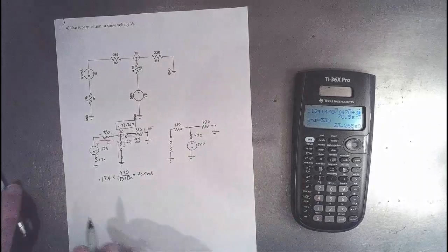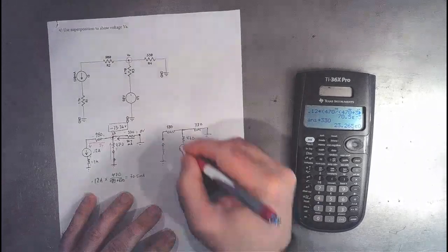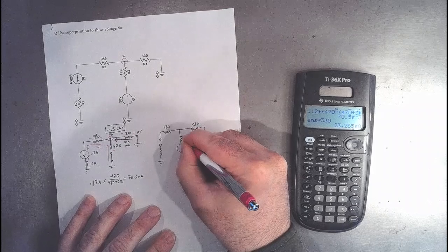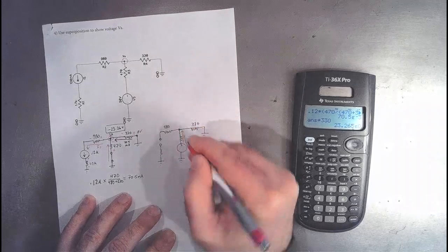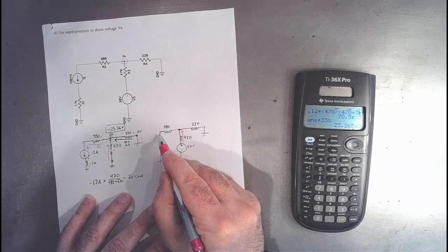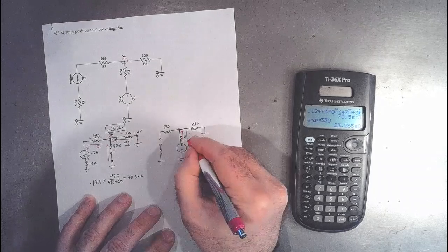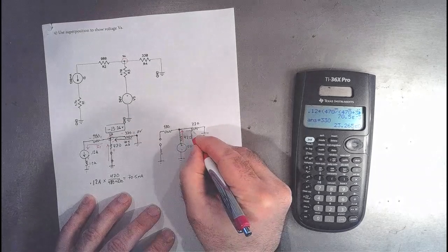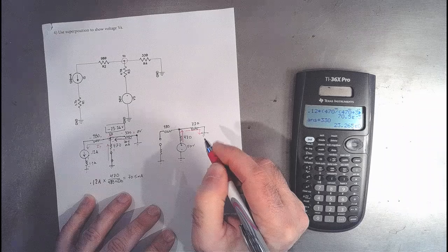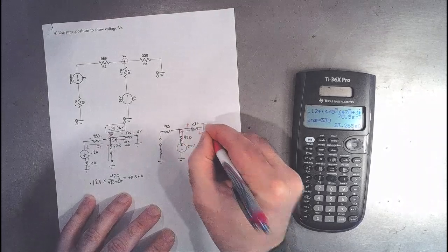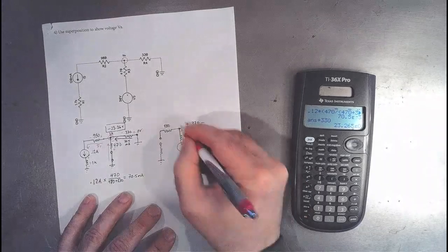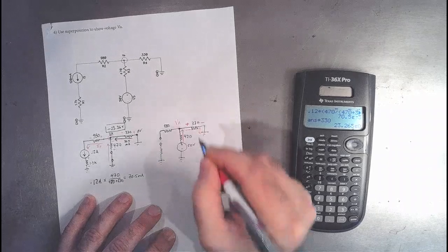All right, now let's look at what the current is doing. It's leaving the voltage source, right? And it flows into this node. Does any of it go to the left? No, because there's no path for that current. So all of it just continues on to the right, like this. All right, well, if I knew the drop across the 330 right there, then I could know what VA is.